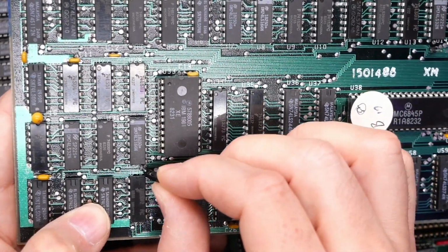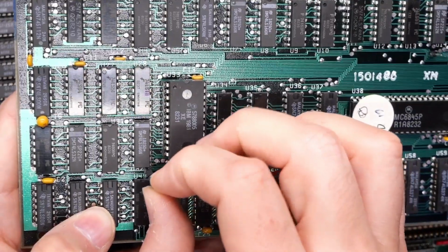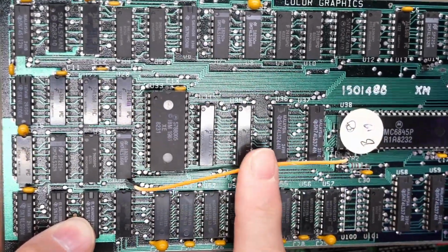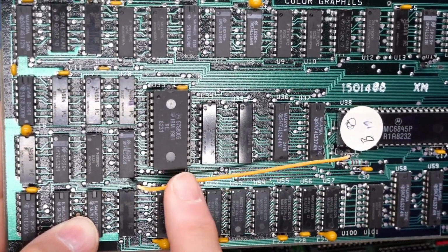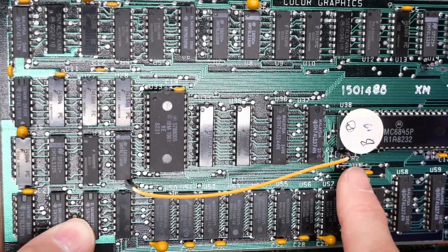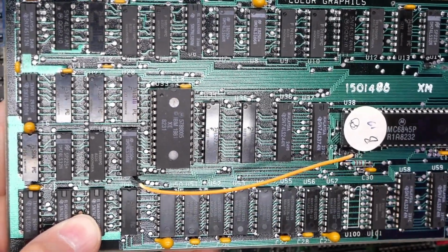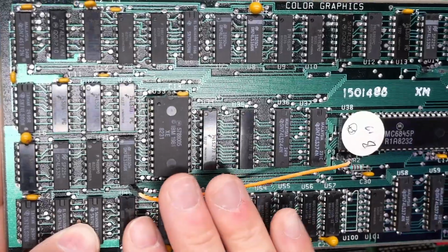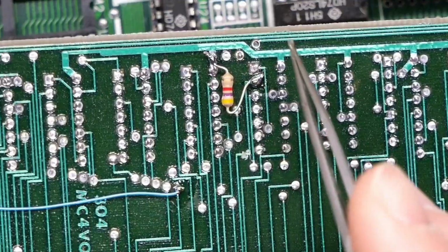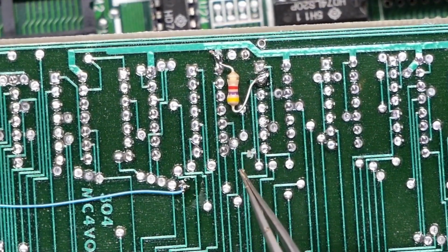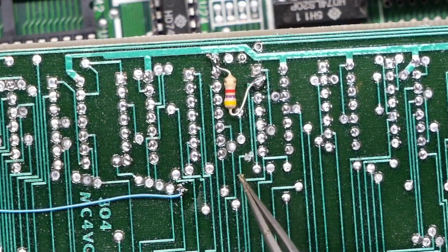Then all you need to do to enable that extra character set for the flashing is just install a jumper wire between those two wires. If I take this off, this will just be double wide font all the time. If I put a jumper on there, it'll be a single wide all the time. So nothing was cut to do this particular mod. The next mod disables the flashing when you type dir in exchange for snow.